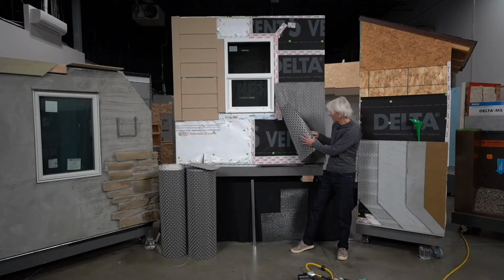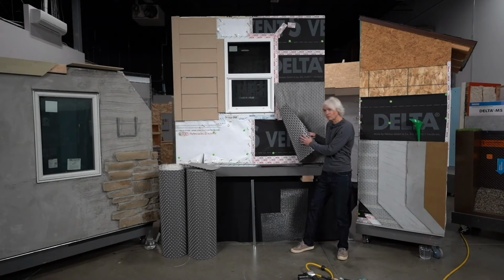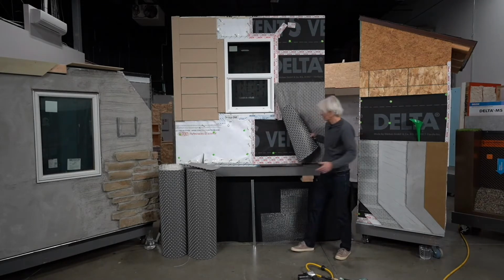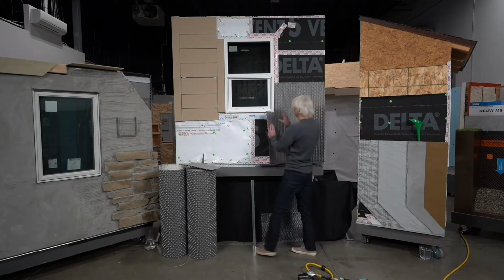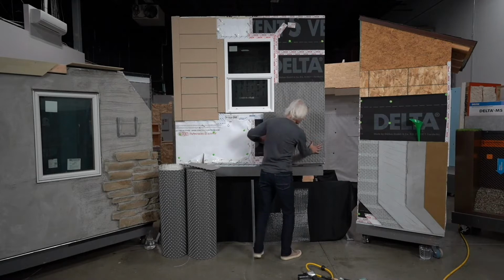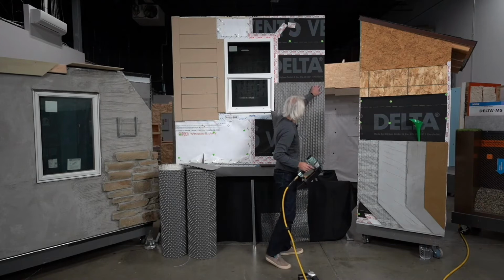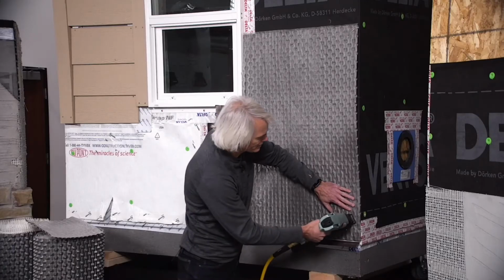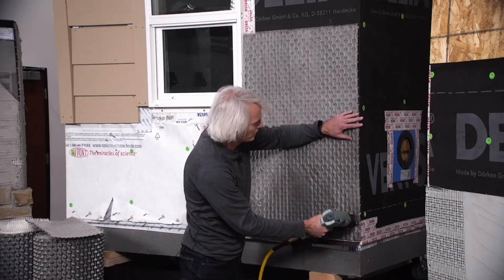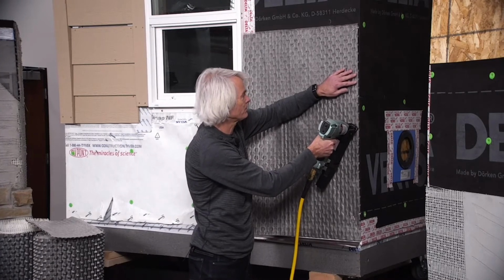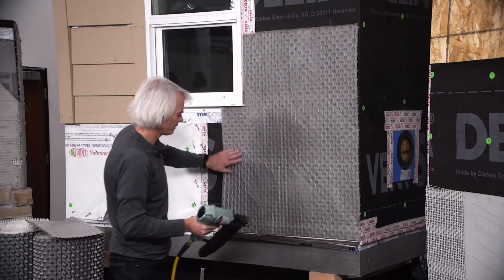Now this Delta Dry Stucco and stone product is going to be applied over the top of our weather barrier and flashing system. So that's our first piece. So we've just pre-cut one small piece to go on here, and we can just install standard staples. We've installed 2 of them up here already, and I'm just going to come right along the edge of the wall and install a few staples just to hold it in place.